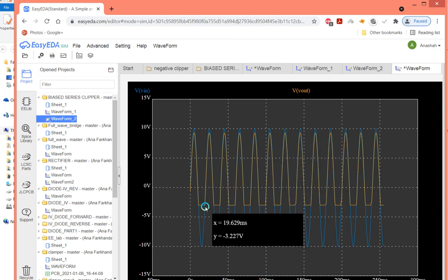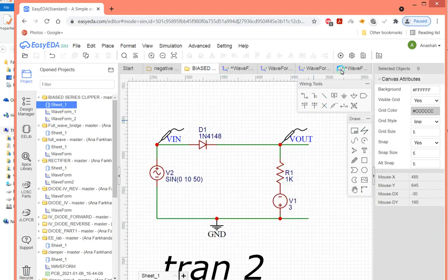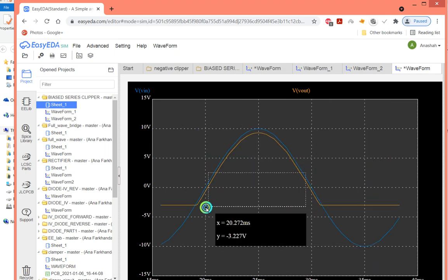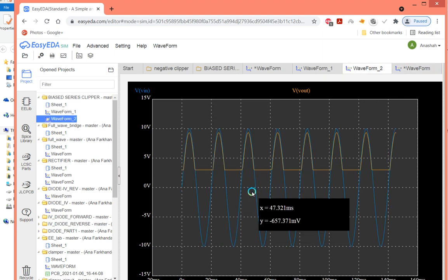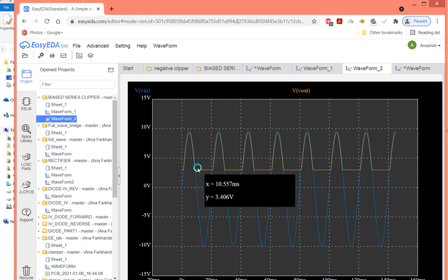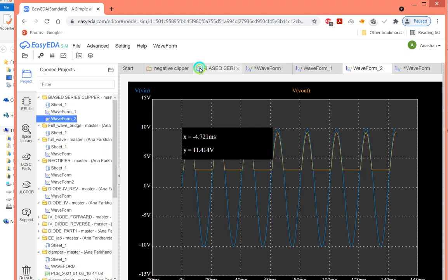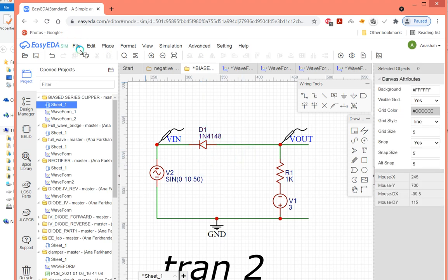Now it's just like the negative part of the battery. So the value of the battery is 3 volts, you can see, but it's minus 3. So here all the value of the waveform below minus 3 has been clipped off, whereas in the earlier it was plus 3. So plus 3, it was above the reference. Plus 3 ke niche jo bhi tha, that was clipped off. And now since we changed the terminals of the battery, now everything below minus 3 has been clipped off. Now if we want totally the reverse, we need to change the orientation of the diode. So then it will be like the reversal of the,